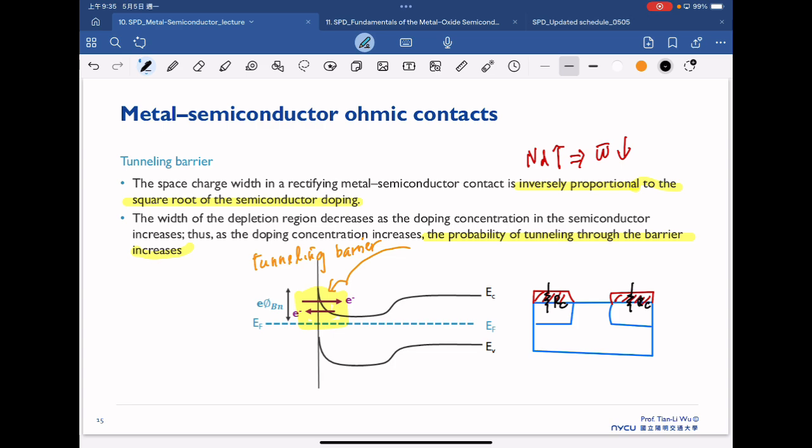In this case, we can make this N++ in the doping source and drain region. N++ means that the doping concentration is increased. The purpose of making a higher doping concentration in this junction is, in the end, to reduce our contact resistance.